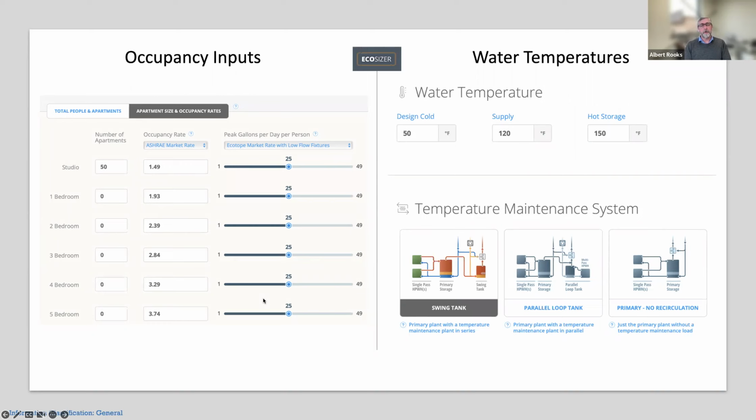And then hot storage. So depending on whose heat pump we're using and what its output temperature is, that's hot storage. The thing about CO2 is I'm really good at CO2, because that's really what I work with. There is no defrost. There's no defrost cycle that we need to deduct. There's no derating. I can literally say design temperature, supply temperature, and 150-degree fixed temperature. Doesn't matter if I'm in Vancouver, BC or San Diego, all good. I don't need to make a climate response.